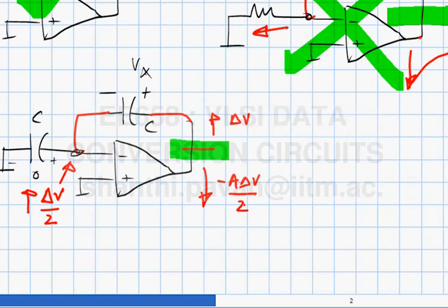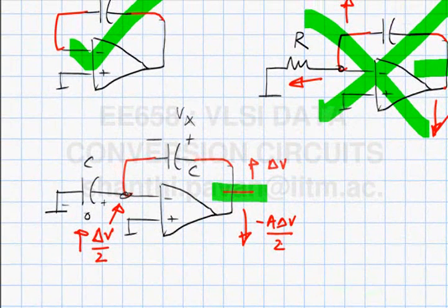So there is definitely DC negative feedback. However, the loop gain for DC is now 1/2 of what it was when this input capacitor wasn't there. This is very similar to the resistor situation. So there is DC negative feedback here also.